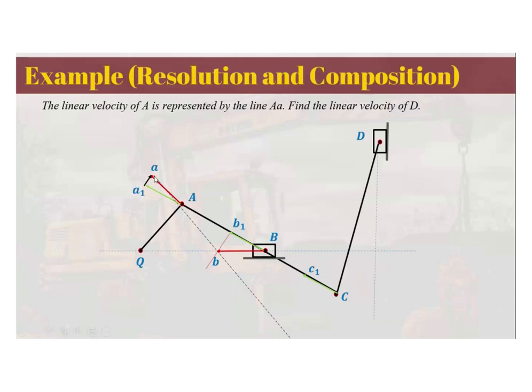As you can see, the head of A, the head of B, and the head of C must also intersect this line. So draw a perpendicular line to the head of C1 and intersect it with this line. Then connect the origination of C to the point of intersection. That is the absolute velocity of C. So now we are able to obtain the direction of the absolute velocities of A, B, and C.